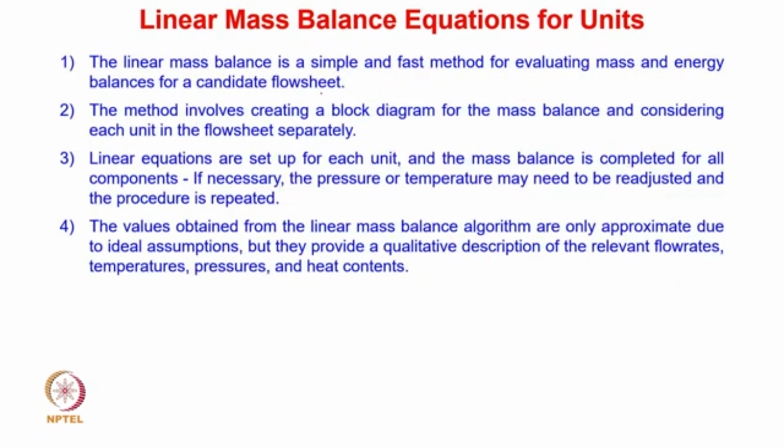So clearly linear mass balance is a simple and fast method, because we are only formulating linear equations. Linear equations can be solved efficiently by using methods like the simplex algorithm, and we can evaluate the mass and energy balance for the candidate flow sheet approximately. The method involves creating a block diagram for the mass balance, considering each unit in the flow sheet separately.